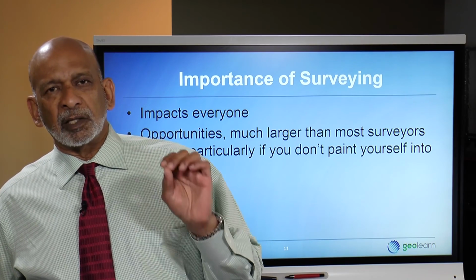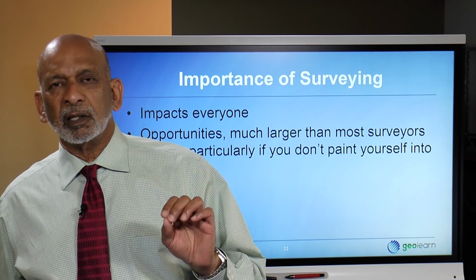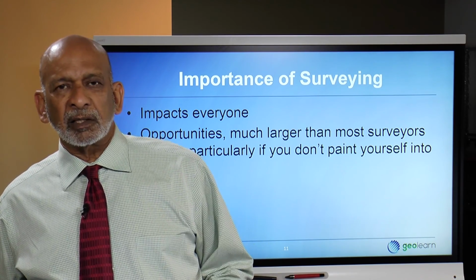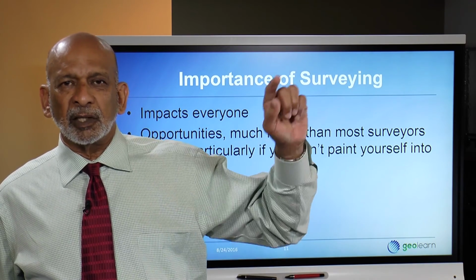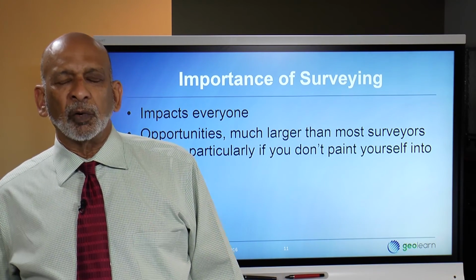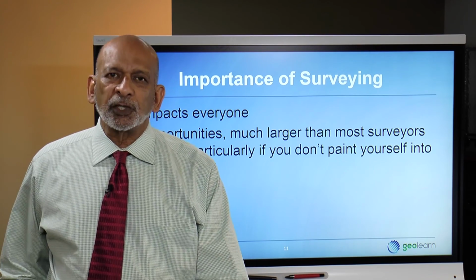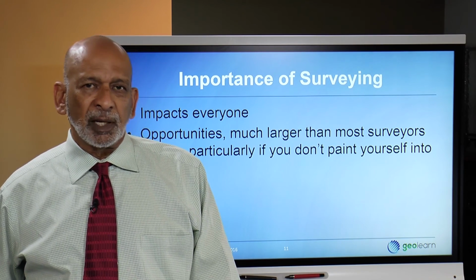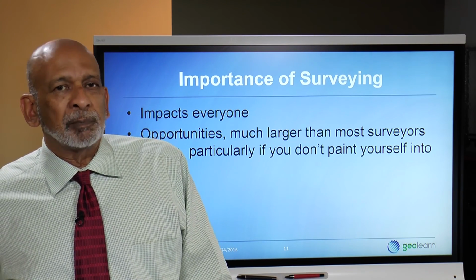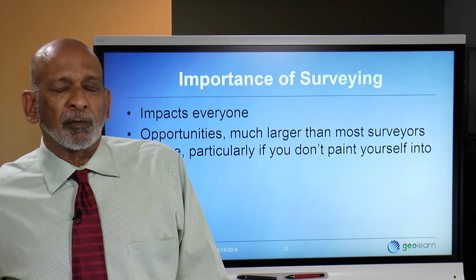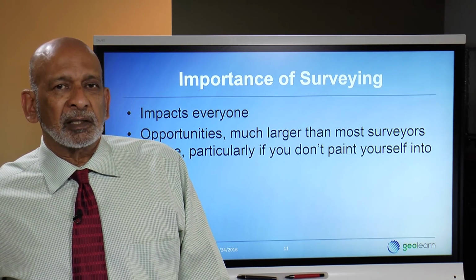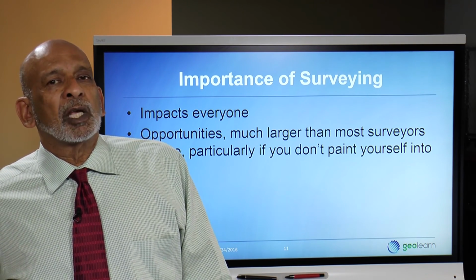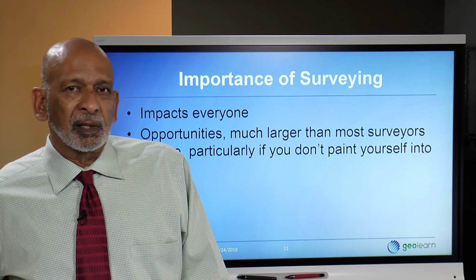So the generators that generate 60-cycle AC current that are on a network, they might be hundreds of miles apart, all need to be synchronized so that that AC cycle they generate is synchronized with each other. You can only do that by having microsecond timing. So microsecond is millionth of a second timing, and GPS is much better than that. It's probably picosecond, which would be billionth of a second timing that you can get from GPS. So they'll often use GPS receivers today because it's a much cheaper way to keep time control. Computer networks, same thing.